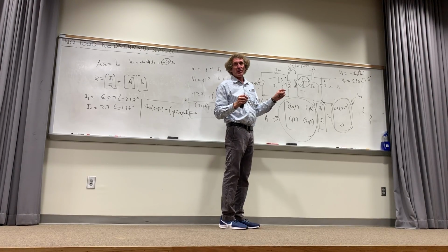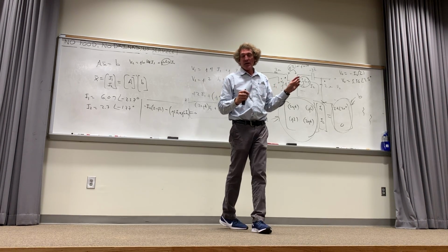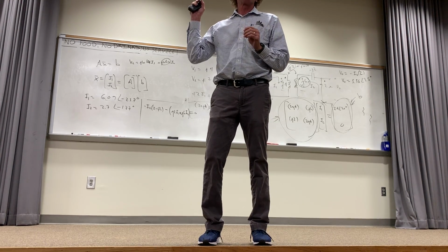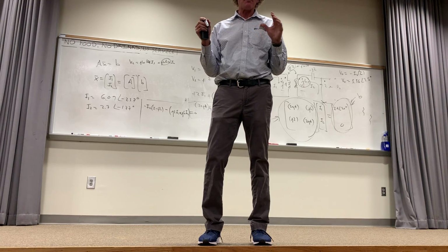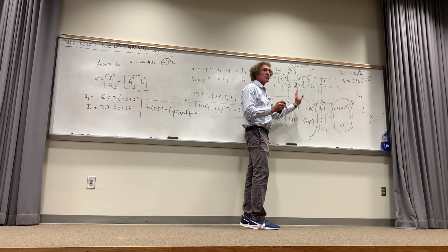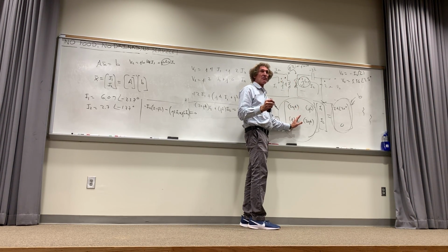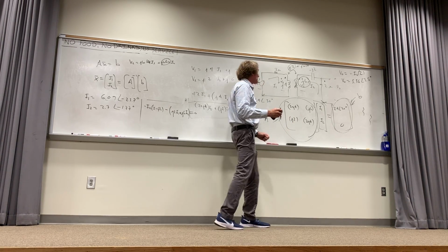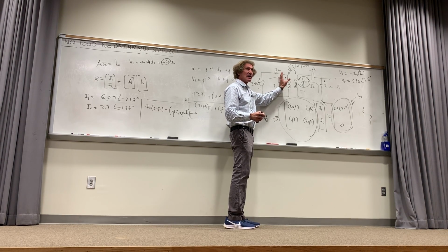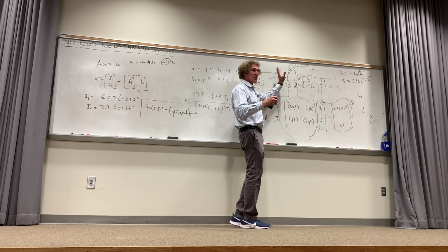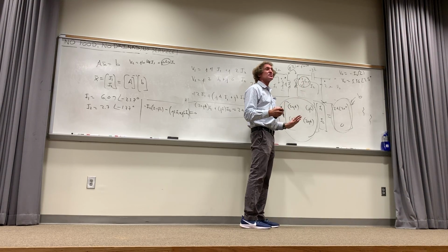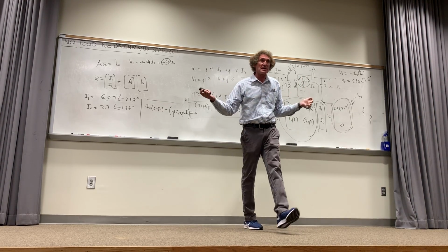And I want to say this too, because some of you MEs are going to be seeing this kind of stuff. If you're working on Teslas or on any of the drones, with a lot of internal combustion and electrical power combined together, you're going to see possibly more than 2 windings. You may say 1 in the primary, 3 or 4 or 5 on the secondary. And you won't have just I1, you'll have I2, I3, I4, and so on. The voltage on the primary is going to be j omega L of the primary times I of the primary, plus j omega M, the mutual between this coil and one coil, times the current flowing in that coil. And you're going to get a system of equations where the matrices can be 6 by 6 easy, right?